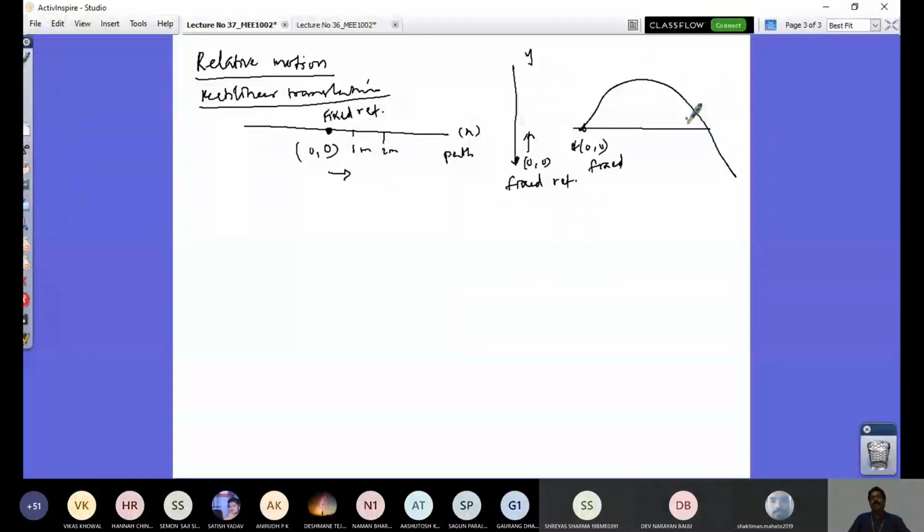But now there are situations, there are design requirements of mechanical systems which are having more number of elements under motion. If I take an IC engine, an engine has got many number of components. Piston is reciprocating, connecting rod is undergoing curvilinear translation as well as rotation, and then crank is rotating. So I have different elements undergoing different motions.